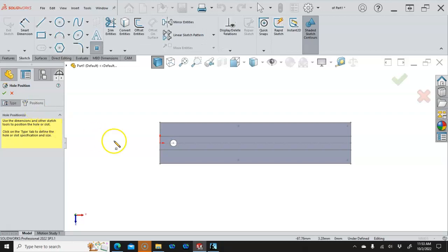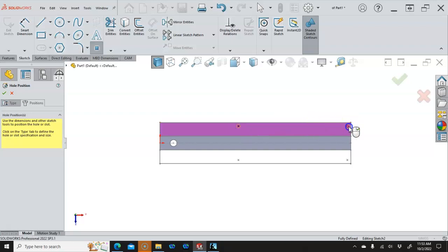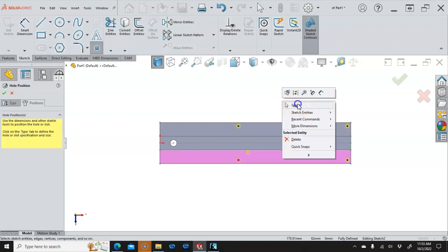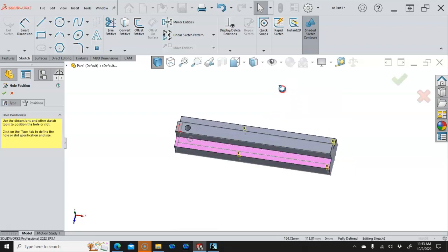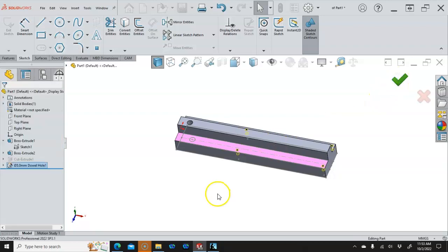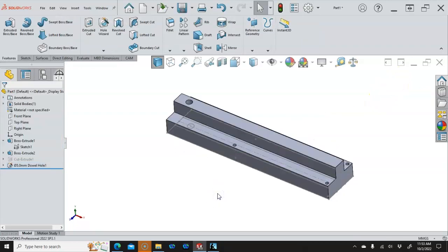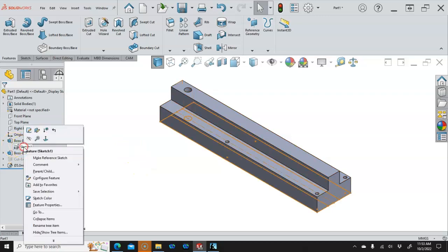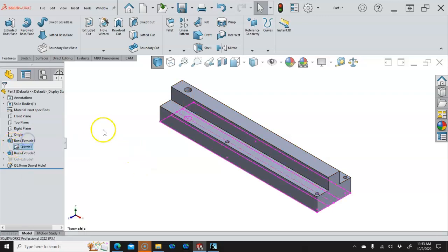All right, so going back into the positions, the hole wizard is automatically going to go into point, and wherever you put a point, there's going to be a hole. So we'd go point, point, point, and point. I'm just looking for those to be coincident with the existing and generate the sketch. And now I can hide that sketch.